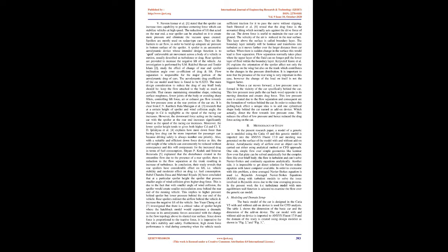The streamlines around a vehicle show the flow pattern around the vehicle, as shown in Fig 1. When the vehicle moves at a certain velocity, there is a formation of a thin layer called the boundary layer. Within this layer the viscous effects of the fluid are dominant, and outside this layer the inviscid effects are dominant. As the flow moves towards the rear part of the car body, the boundary layers separate and the fluid flow is detached. The boundary layers lose kinetic energy and swirl around to form vortices, and result in drag and wake formation.